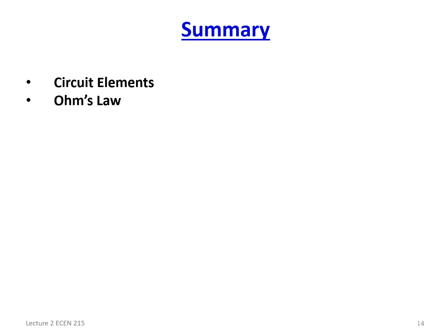And of course, correspondingly, we have the power equation, P is equal to V times I, and hence through Ohm's law in that equation, we're able to get equations such as power is equal to I squared R and V squared over R. Again, very useful equations to know because one of the very common questions asked in the homework and in some of the test questions is what is the power in resistor 5, or what is the power being supplied by the 5-volt power supply, things like that. And you need to know both the current and the voltage to be able to solve for that.